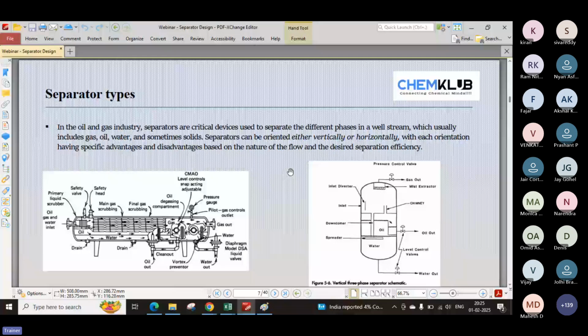There also we require separation to separate the uncondensed gases, then the lighter product, that is the main product, which will go as reflux as well as product, and to remove any higher volume or high density fluid coming to the top of the distillation column. That is why a separator is a typical one we require in industry.